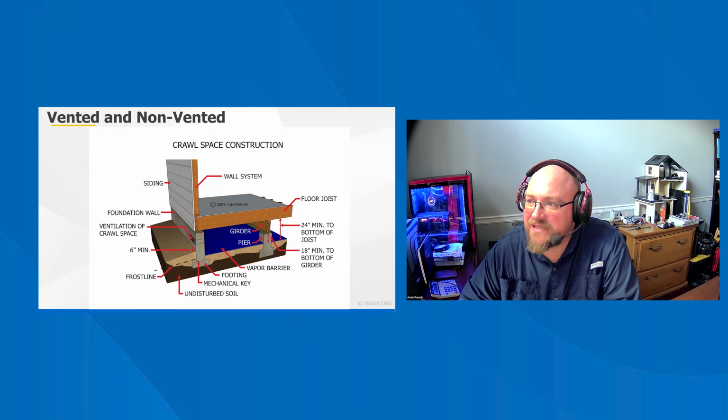The ventilation openings should be at least 1 square foot for every 150 square feet of underfloor space unless the earth ground surface is covered by a vapor retarder installed within 3 feet of each corner of the building.